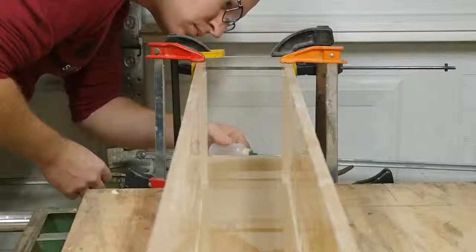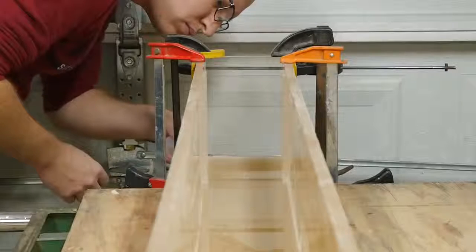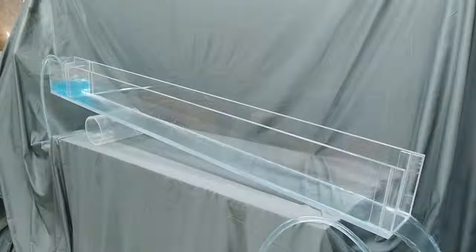You can see the fast-moving flow right as the stream hits the sink and the abrupt transition of the hydraulic jump to a slower-moving flow. But the sink demo isn't the best example because it happens due to surface tension, not gravity. Plus it's kind of boring, so I built this flume in my garage to give you a better look at the hydraulics.